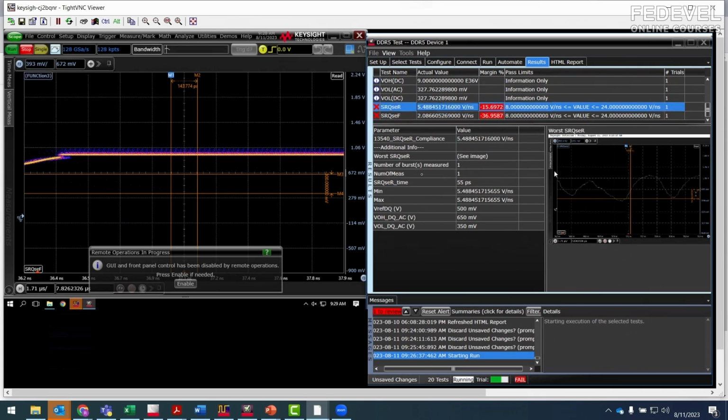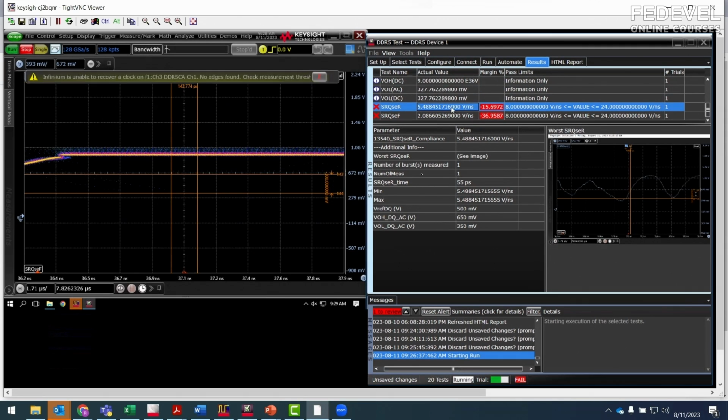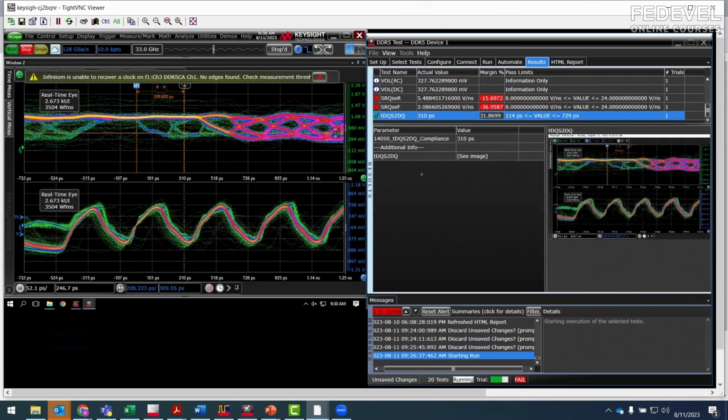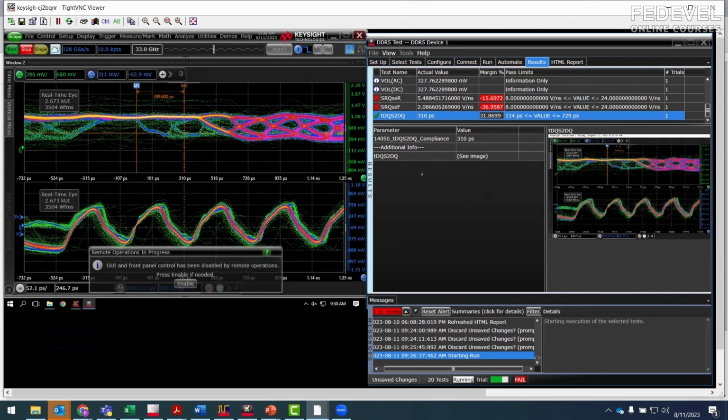And this could be a rising edge, also caused because we use the interposer and connected probes. Exactly. Yeah, that's a really good point. And if I were to de-embed the interposer, I can guarantee the rise time will be faster, and this slew rate would be much better. So we definitely need to have a look at these numbers, for example, how far they are from the tolerance, and maybe if it's very close to the tolerance, we can consider them still okay.